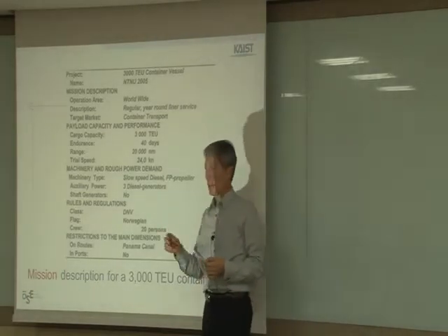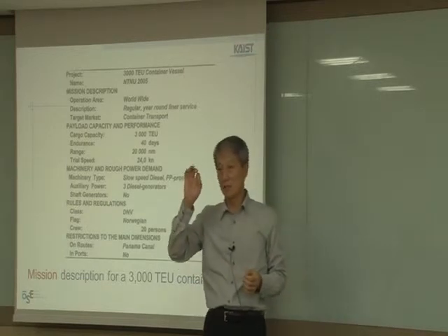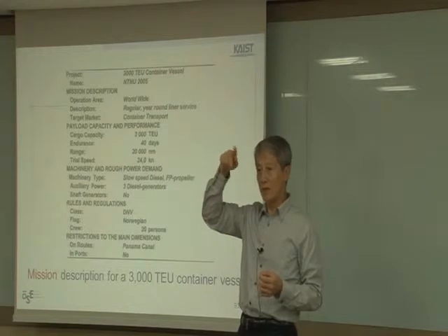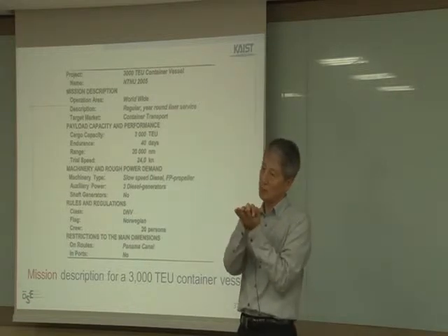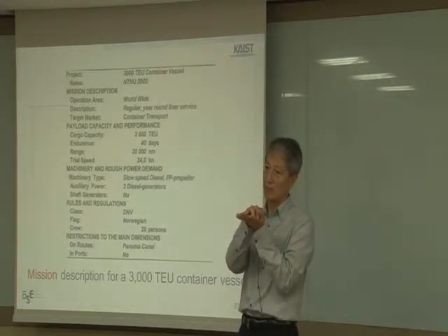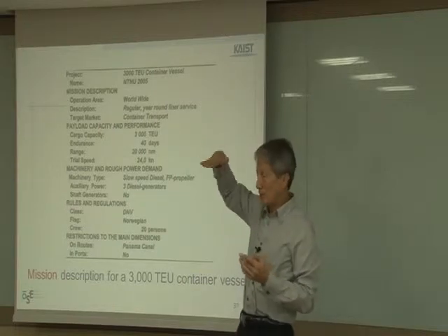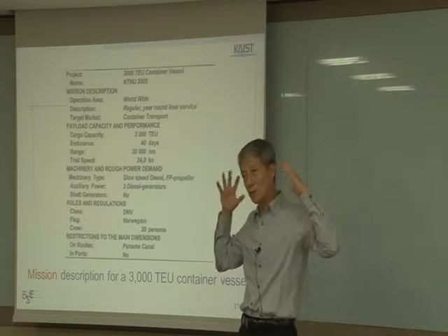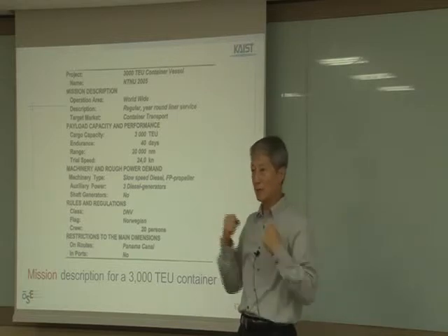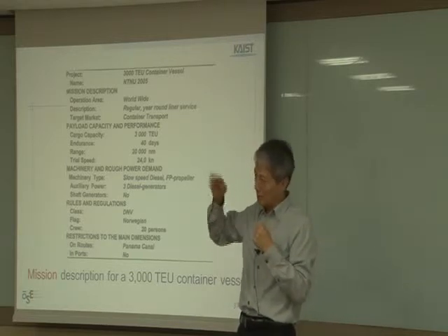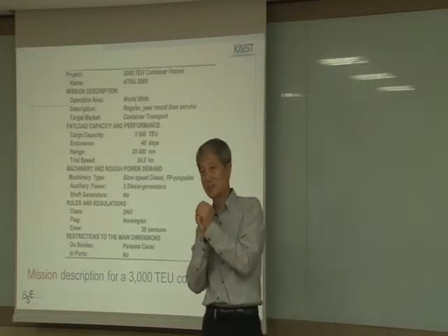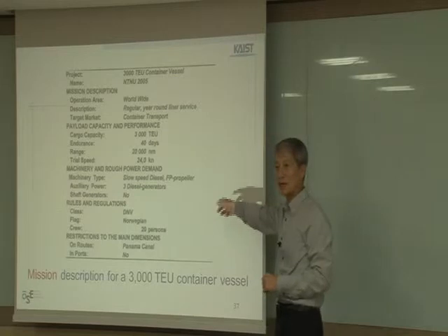Right. So gas turbine, the airplane has a gas turbine, right? Their RPM is very high, so the engine is very small, lighter. Because an airplane should have a smaller, lighter engine, but the power should be big. So they adopt the gas turbine because it is very high speed, high RPM, smaller size. But for a ship it is okay.